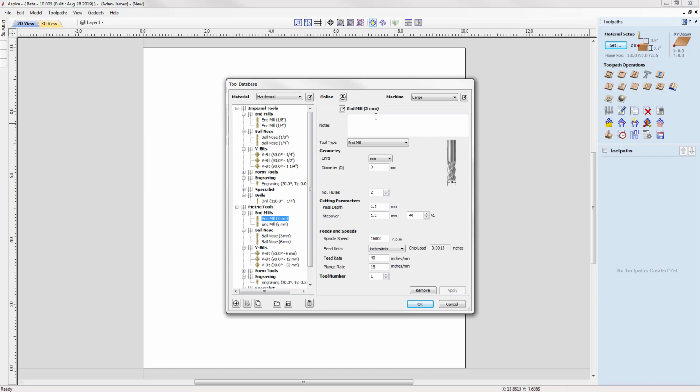So every tool supports a tool name, listed up here, a tool notes field, and this can be helpful to include reminders about properties of the tool. The tool notes can also be output by the post-processor depending on the controller, and that may be useful for some post-processing operations. They always include a diameter of some form and the number of flutes.